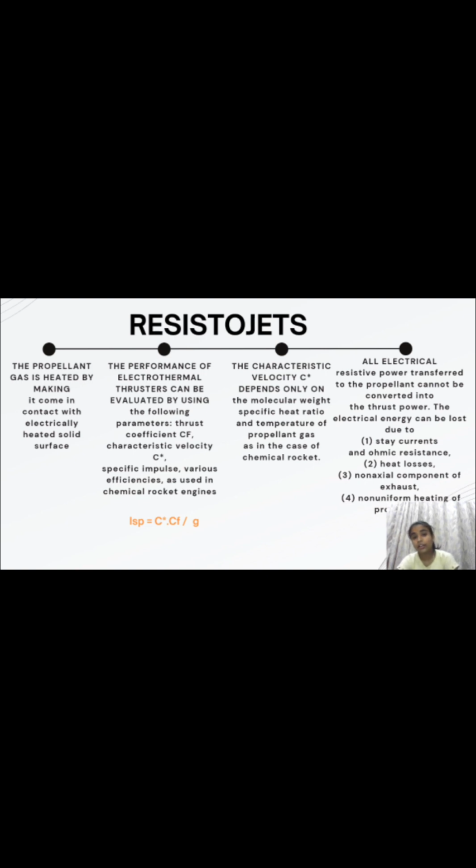Then the third point which I have written in the slide is that the characteristic velocity depends only on the molecular weight. What does this statement mean? Molecular weight is the average weight of the molecules in the rocket fuel. Lighter molecules contribute to a higher characteristic velocity. Specific heat ratio is a measure of how much the gas can be heated. If the gas can absorb a lot of heat, it can generate more thrust, contributing to a higher characteristic velocity.